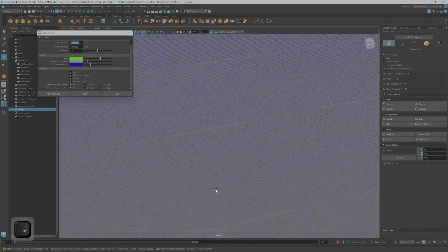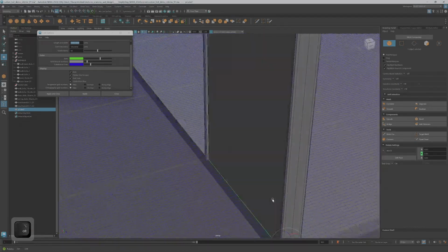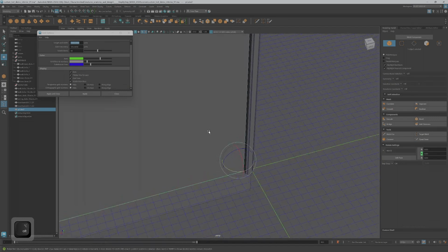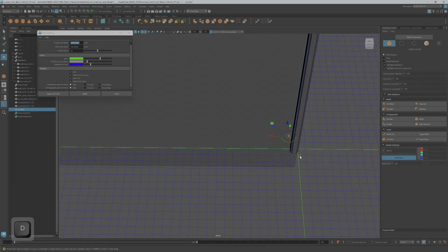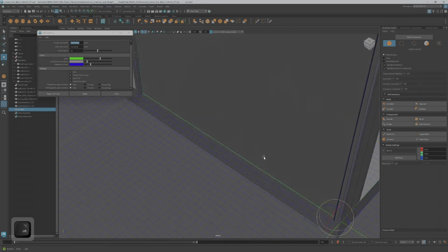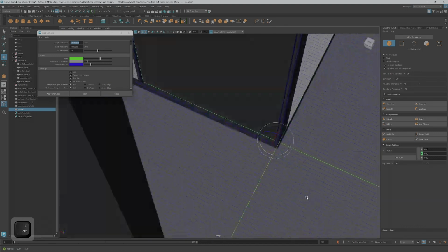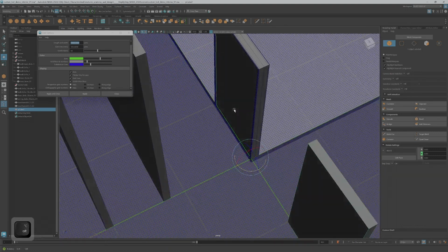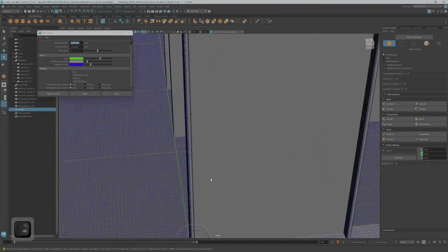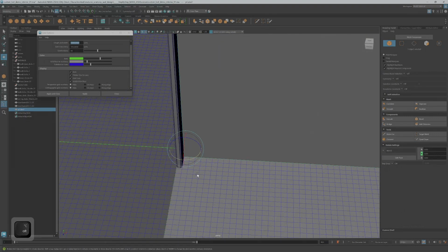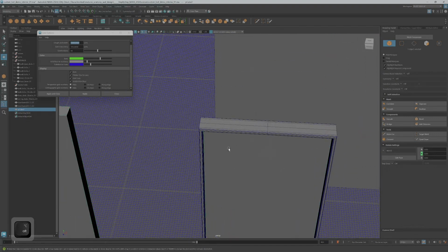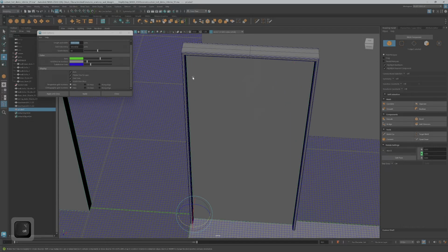If I wanted it to swing from the other direction, I would go to the outside of the door and hold down D and V, drag it to the other pivot, and then from there, we can have an outside swinging door. So that's really your call, how you want to do that. It's all snapped to the grid, nice and even, except for the very top. I kind of went off grid a tiny bit with my bubble. It's all right.